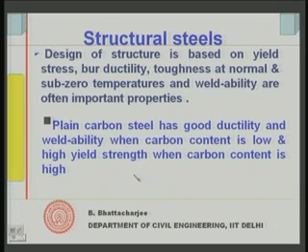Plain carbon steel has good ductility and weldability when carbon content is low. Why it is so, we will try to see right now. Its yield strength increases when we have high carbon content, although we may not have ductility. We cannot get both things together. If I get ductility, I normally do not get high yield strength, and if I have high yield strength, then ductility is low.